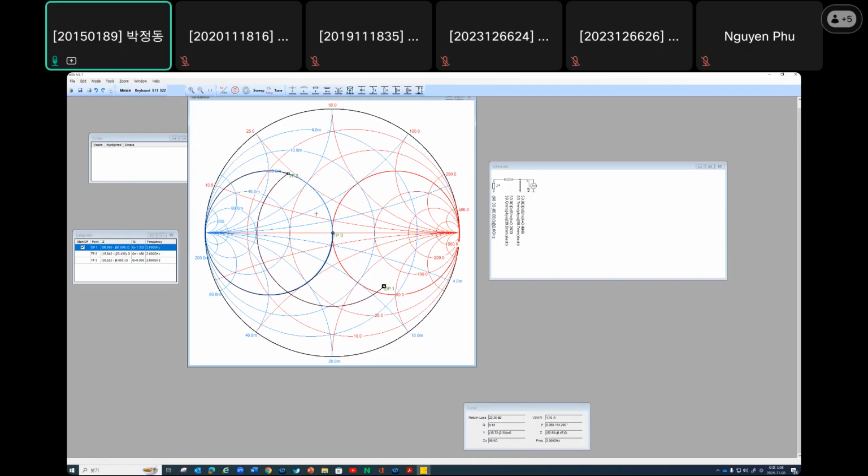As you can see, if your required shunt stub, before resonating out, has an impedance that is reactive, inductive, you have to use a capacitive shunt stub.